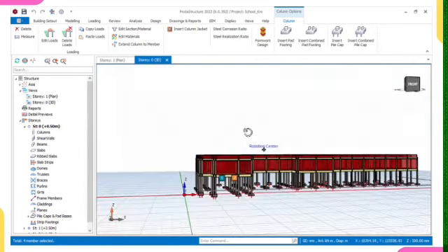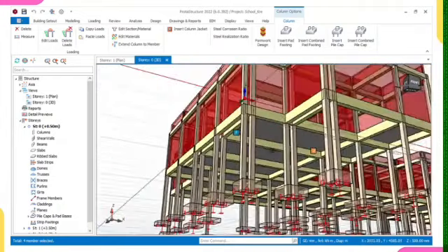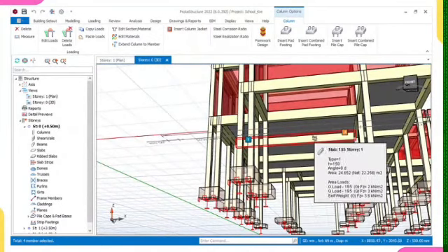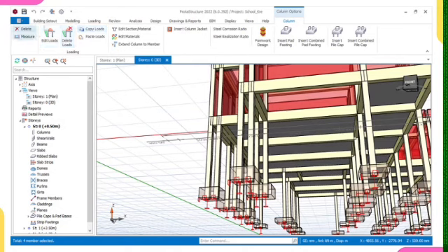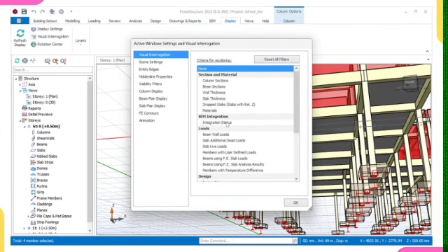So if you can see, we're having some of our beams spanning above 6 meters. These are the beams spanning above 6 meters. And the depth that we use here is 650 millimeter beam depth, because the span is 7.2 meters. So I'd like us to go to the design. Let's know whether all our members pass.